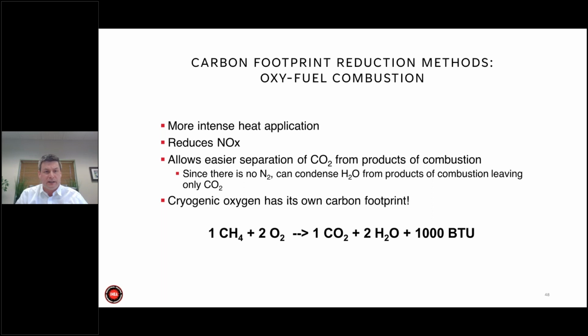You want to take a look at carbon separation technologies. However, as we talked about earlier, cryogenic nitrogen has a carbon footprint, and cryogenic oxygen is going to have a higher carbon footprint than that. The same way you make cryogenic nitrogen is the way you make cryogenic oxygen, but there's less oxygen in air. So you have to account for the amount of carbon being put into the oxygen before you even burn the fuel to see if it makes any sense.